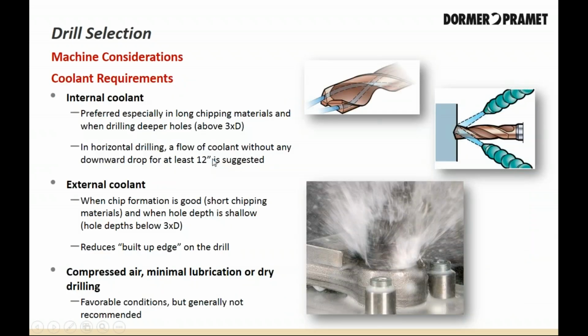Coolant supply is essential in drilling and influences chip evacuation, hole quality, and tool life. Use of internal coolant is almost always a plus when drilling. Always look for ways to optimize coolant delivery. Optimal coolant delivery will allow for better penetration, better chip flow, and enough coolant tends to keep the tool substrate from getting too hot, which causes premature failure as the cutting edges break down.